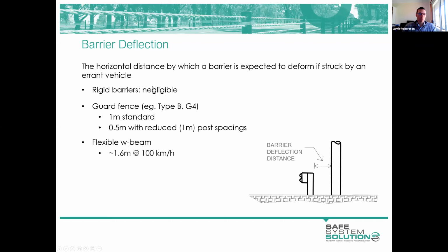They can even advise a maximum expected deflection for a specific situation. If you can tell them your cross-section details and where you're proposing to install the barrier in relation to the road, they can determine some sort of maximum expected run-out angles and corresponding deflection. So I do encourage you to contact your suppliers if you're in a constrained situation and you can't afford the standard deflection.